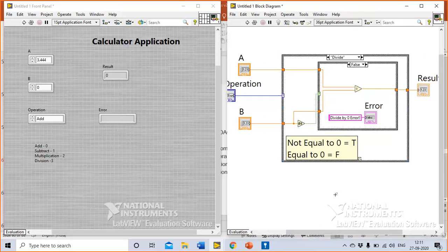Sir, in the outer case structure, on the upper boundary, there are 4 cases: add, subtract, multiply, and divide. But in my case, all 4 cases are add only. Okay. You can simply come here and rename these as well. Simply double click and rename, or first figure out whether in your enum, do you have 4 different cases, or are all of them add? All 4 are different. Now in the case structure, for some reason you have got the same ones.